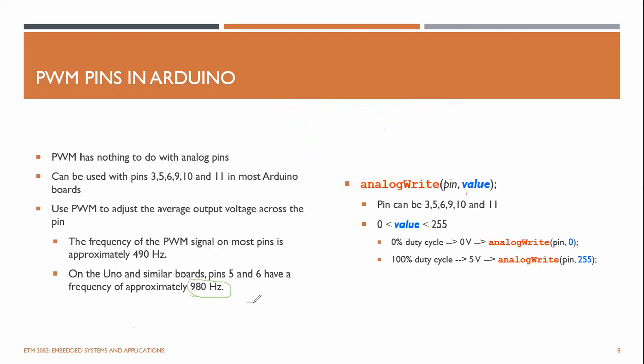The duty ratio is the thing that you use to control the speed, right? It will work for both of the frequencies. So by changing the duty ratio, you can adjust the speed. Changing the right frequency depends upon the motor inductance and everything, but at this stage, forget about that. Assume it will work for both frequencies.